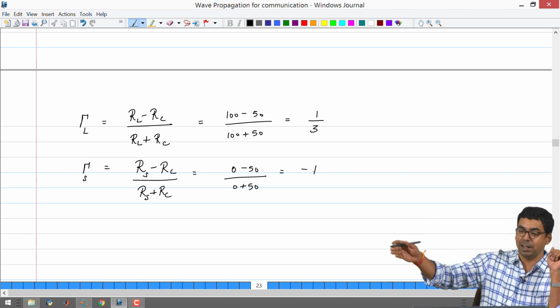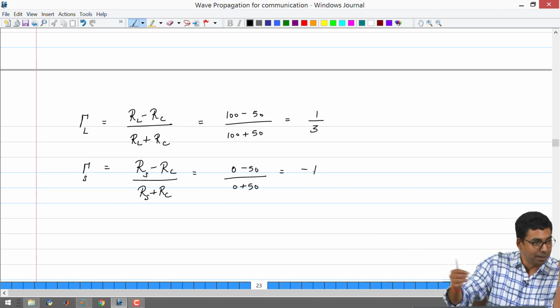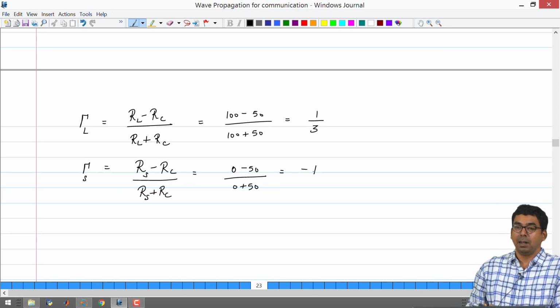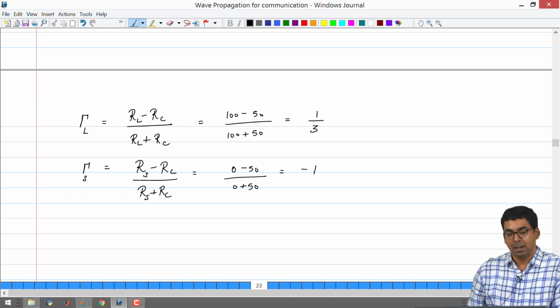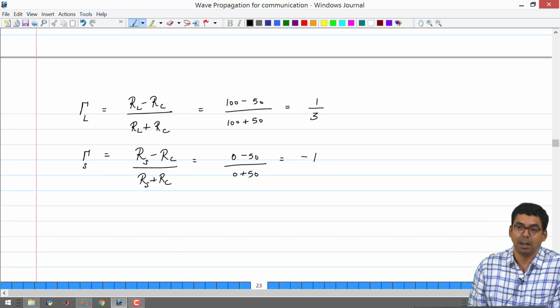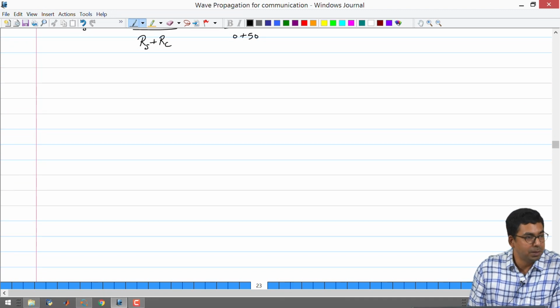Once it reaches the right hand side, 1/3 of it is going to get reflected back and then it is going to flip, and so the voltage profile in a transmission line for such a simple circuit is going to change with respect to time. It is going to change dramatically. And one of the ways to track what is happening in the transmission line is by drawing what are known as bounce diagrams.